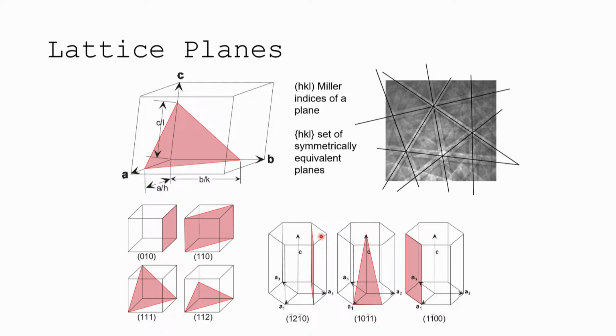All right, now if we do this for hexagonal or trigonal systems, it's the same strategy, but now we define these planes as different types of indices. If we take our hexagonal prism here, it's cutting through only the A1 axis, and then negative A3 and negative A1 axes, so A1, A2, A3 positions, and it cuts through here at a half, it cuts through 1 at the other positions. So this would be reciprocals. So instead of half, 1, half, it's 1, 2, 1, right? So 1 bar. If it's the negative position, we say bar on that.